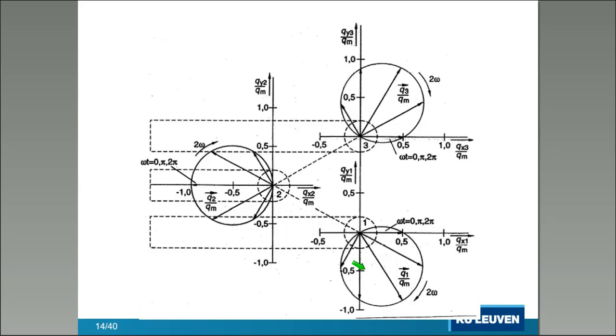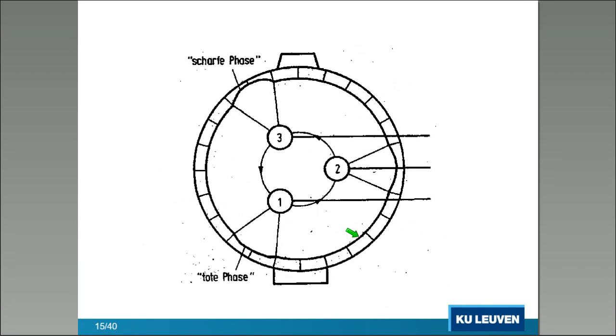I have here again the 3 electrodes, here in broken circles, 1 electrode, second electrode, third electrode for the 3-phase system. And here you see the circle of the movement of the arc. This is not without importance. That means if your system is unbalanced, you can have a stronger movement, for instance, of this phase, and you have an enhanced erosion of the refractory of your vessel here, which is, of course, something you want to avoid.